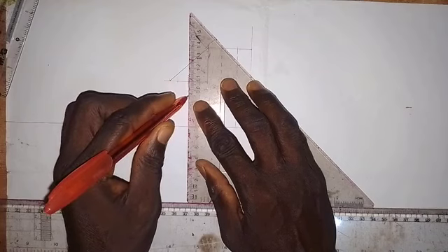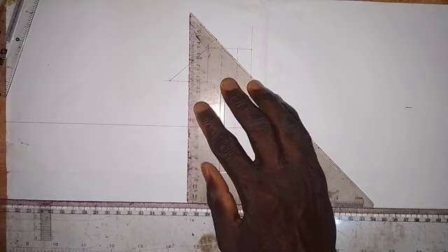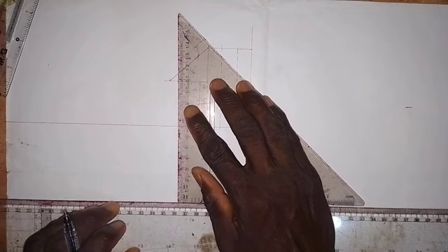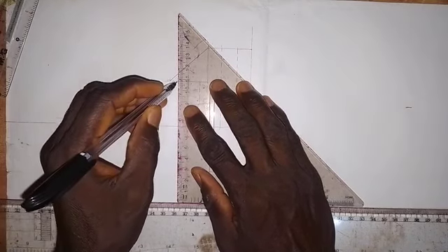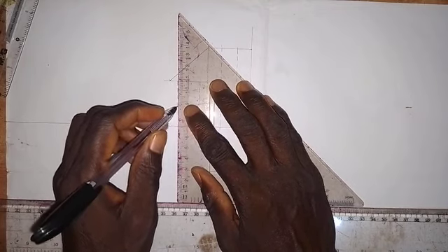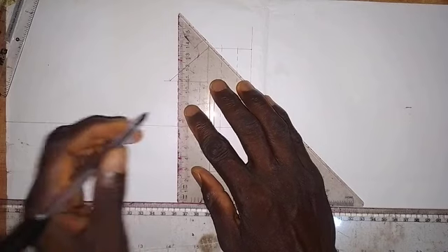The center line is drawn with a thin long chain line. This other part of the hole is also drawn with a short dashes line because it is hidden from us in the front elevation. All right, so we have represented that part.